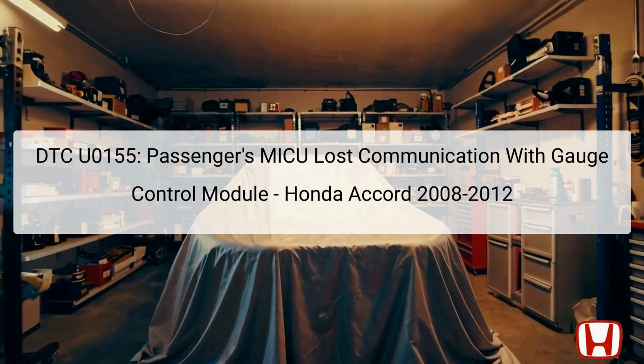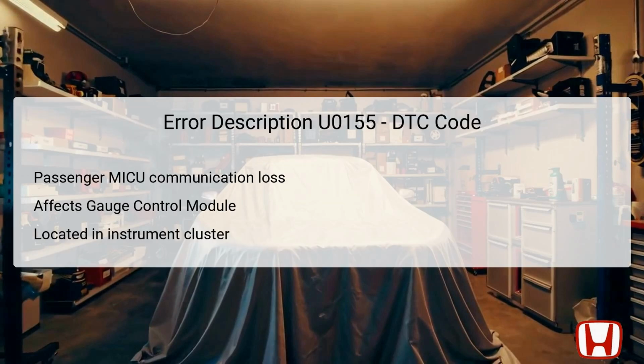The MICU is located under the dashboard on the driver's side, while the gauge control module is typically situated in the instrument cluster assembly. The failure in communication can result from various electrical issues, including faulty wiring, poor connections, or a malfunctioning component. It is essential to accurately diagnose this code to restore proper functionality to the dashboard and related systems. The U0155 error code indicates a critical communication breakdown between the passenger's MICU and the gauge control module.